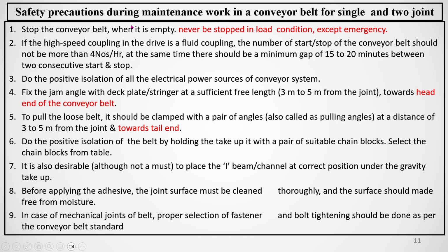Then safety precautions during maintenance work of the conveyor belt for single and two joints. When you are repairing the belt joints, we have to take some safety precautions. What are the safety precautions? Stop the conveyor belt when it is empty. Only when it is empty should you stop the belt.